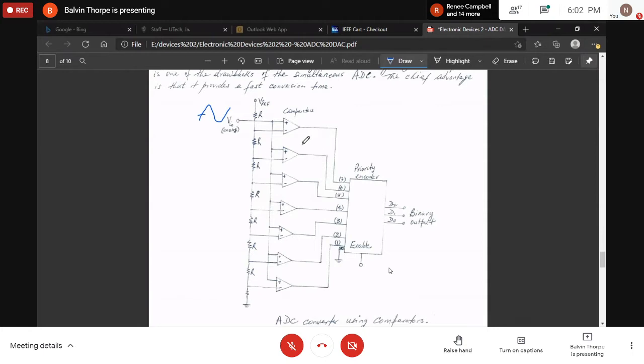It's going to put a 0. Because remember, what's coming out here now is going to be a maximum. Again, because it's a comparator, it's going to be either it's greater than the reference or it's less than the reference. So if it's greater than the reference, and let's say the reference is 7, it's going to say, okay, the signal is greater than 7 right here. Or it's less than 7. And if it's less than 7, it means that when the enable is applied, it checks this one, it sees that it's less than 7. Say, okay, that's not going to give any output value here, eh? So in other words, it's going to output a 0 for this one. It checks this one, it sees that it's a 0. It checks this one, it sees that it's a 0 because it's less than, right?